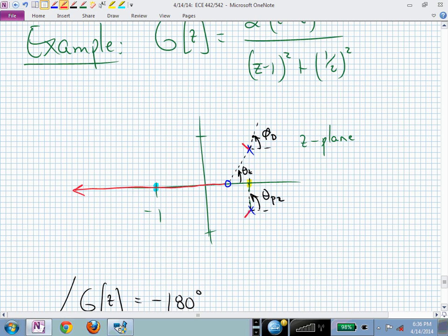Can we figure out how to connect the dots or connect the segments? What else can we find? You know what? This one's not too difficult, actually, if you brought your compass. Because this is a two-pole, one-zero configuration, which means that they are living on a circle of radius equal to the distance from that zero as the center up to that pole.